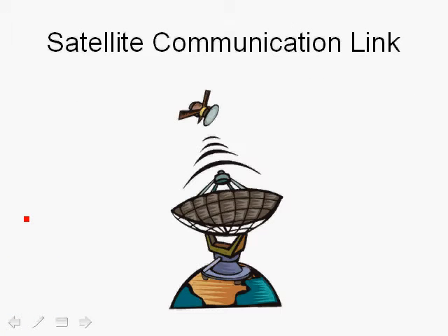Digital communication links are the basis for high-capacity transmission in terrestrial microwave links and in deep space communications with spacecrafts and probes. In satellite communications, the maximum capacity is limited by bandwidth and signal-to-noise ratio. To achieve higher capacity within a limited bandwidth, we use schemes that allocate multiple bits to symbols to reduce the symbol rate, which is limited by the bandwidth. However, due to limited power, the SNR puts a limit on the number of bits that can be mapped to symbols. So there are many issues involved with high-capacity digital communications, even over satellite links.